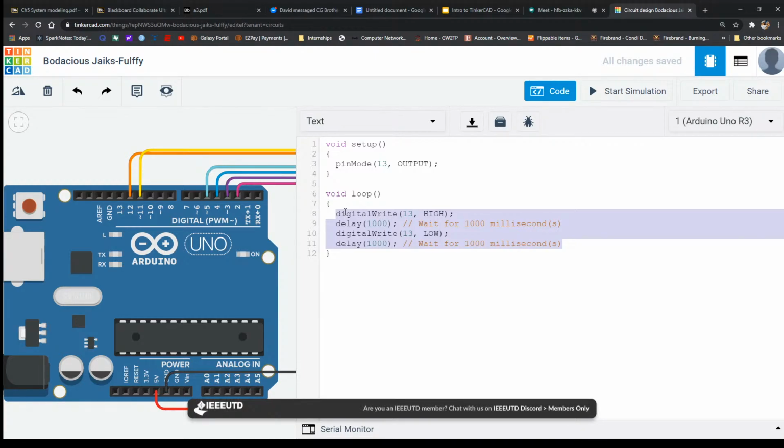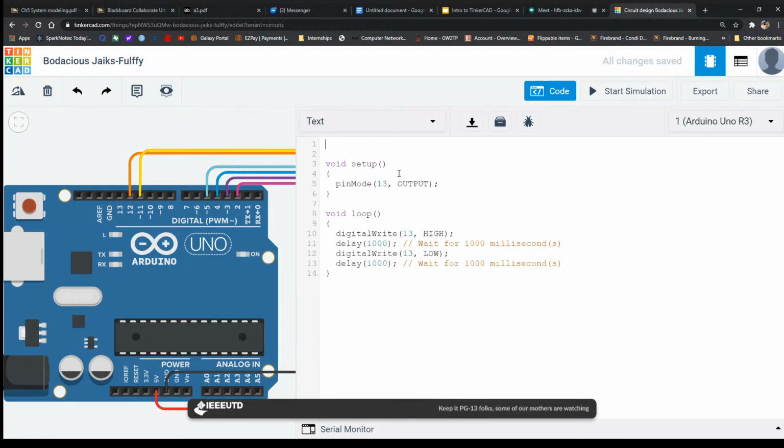What we're going to be using today is the liquid crystal display library. So if you can go ahead and do this, we're going to be including the liquid crystal display library. The way you do it is you type at the very top hashtag include and then LiquidCrystal.h in the less than and greater than signs.